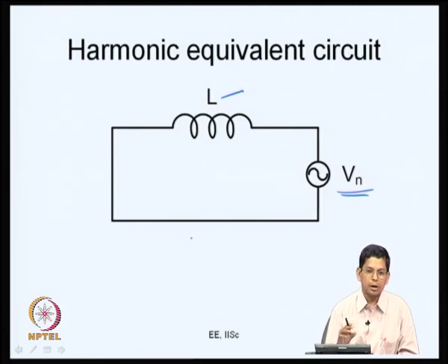So, what we have been looking at is a measure for calculating harmonic current, and from there we will be able to quantify some of the undesirable effects due to harmonics, such as the increased copper loss, etc. As I mentioned, the purpose of pulse width modulation is to control the fundamental voltage and to mitigate the harmonics and their harmful side effects. We have reviewed Fourier series, which tells us how to calculate the fundamental and the harmonic components, and we have developed models, so that given a fundamental voltage or a fundamental current or harmonic voltage, we are able to calculate the corresponding fundamental current and harmonic currents. So, let us continue this in the next class and get into our business of understanding PWM effectively.